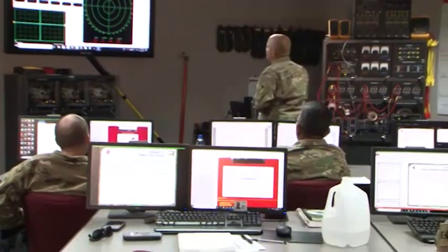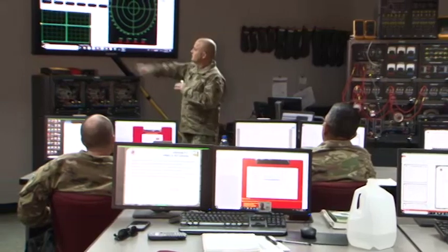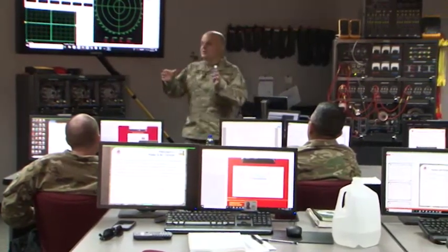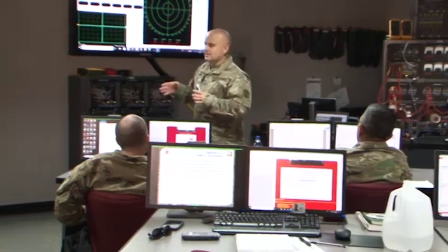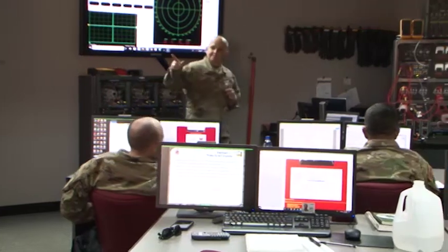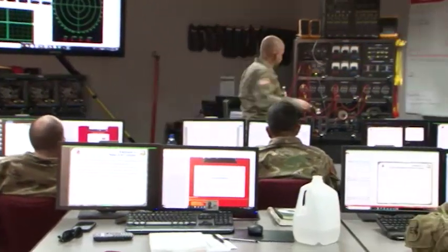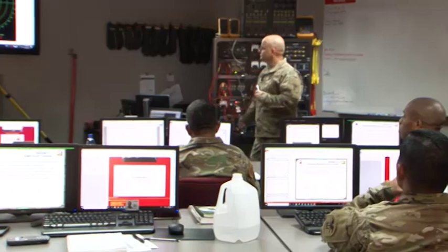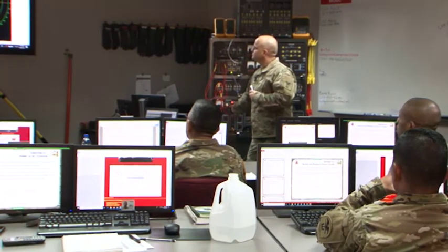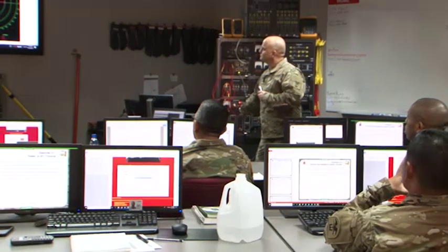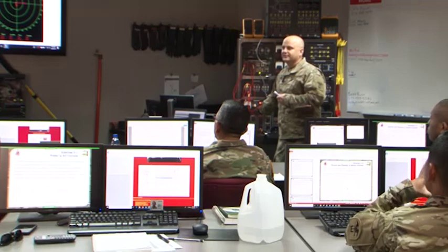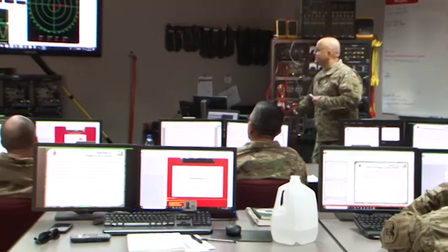Okay. So that means if I just hook up just an inductor and I do this exact same exercise, where is the current going to be in reference to the voltage? 90 degrees off. Which one's going to be leading which? Voltage leads current. Yeah. Voltage leads current? All right, so now what's happening? I'm dialing up and dialing down, right? But we're seeing the same magnitude variation, so that science remained consistent.